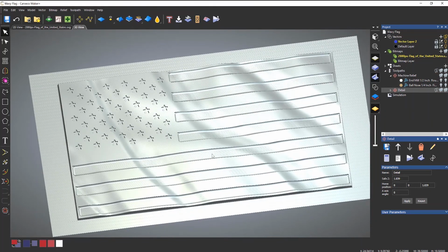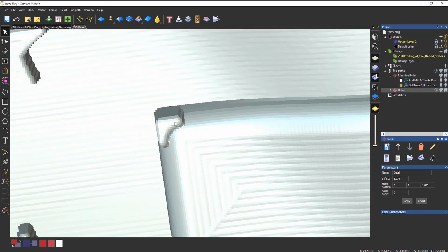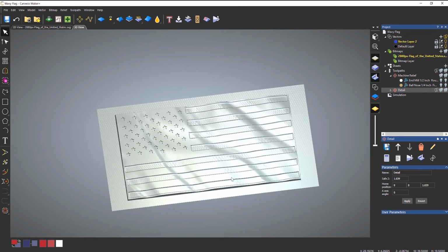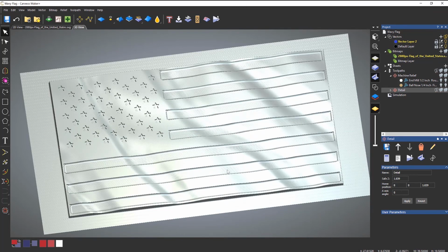Then it drops it on there. Now what I've done, I've made a deliberate mistake, because when you do drop these down, if you use more than one tool, obviously because the ball on the tool is different, you will get a different projection. Okay, so if I zoom in, let's say here, you can see that this is taking out a little bit more than what's needed. So as I said before, you can't undo this.